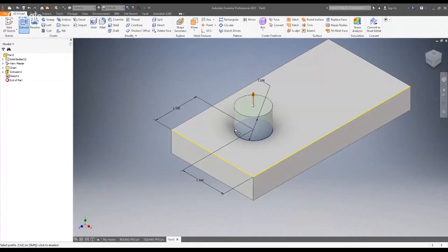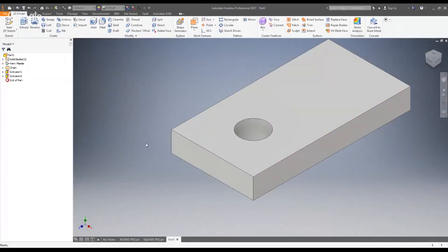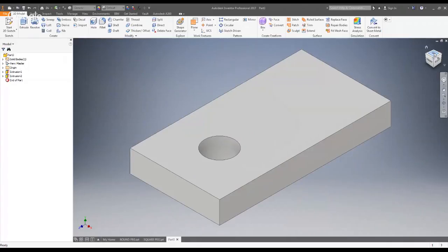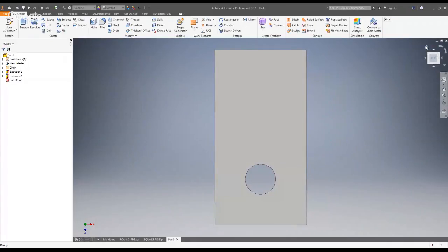That's kind of weird. I want to make a hole, and so right here from the extrude window, I can change the direction of the extrusion here. So I'm going in this direction. Oh, direction 2 looks to work. Goes right through the board. There it was, direction 1, direction 2, and I hit OK. And go to the home view, and what do you know? We have a hole. That's good.